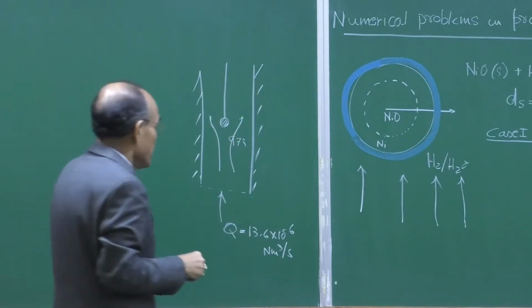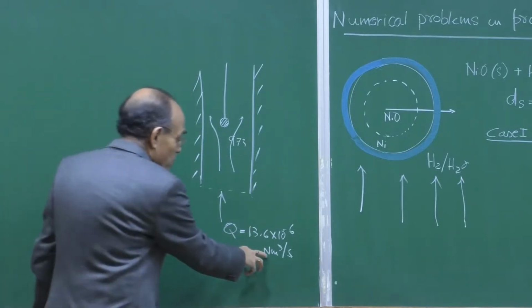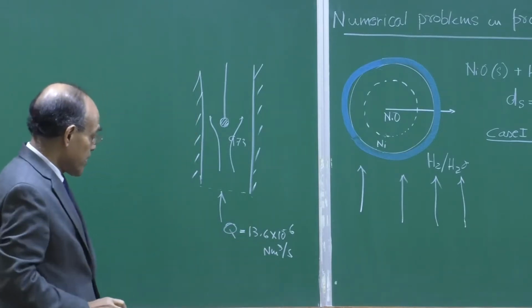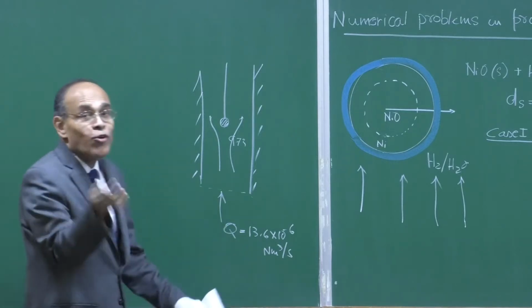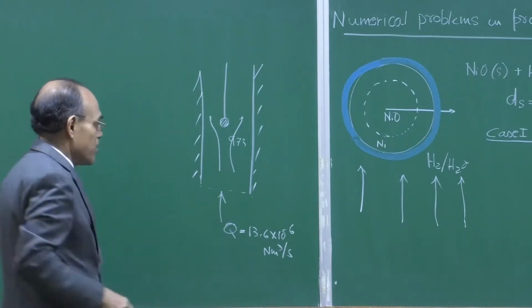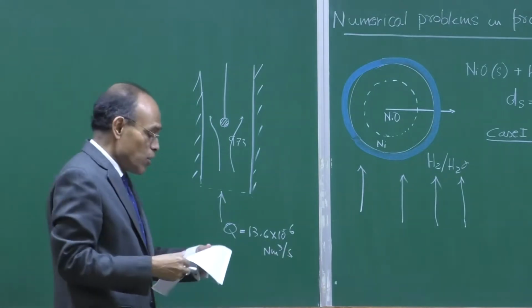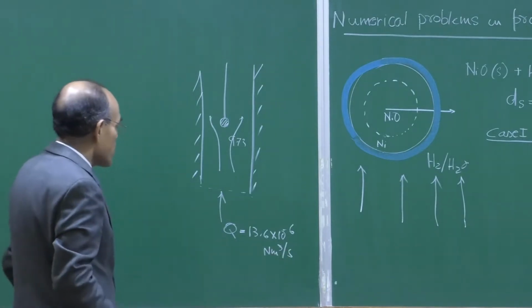Standard is 273, but if it is normal, that means it is 25 degree centigrade, so it is 298. According to the ideal gas law, you can jack up the volume which the particle is actually facing, and based on this, from the normal meter cube per second flow rate, you should be able to calculate the velocity.